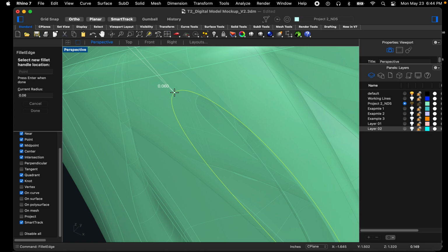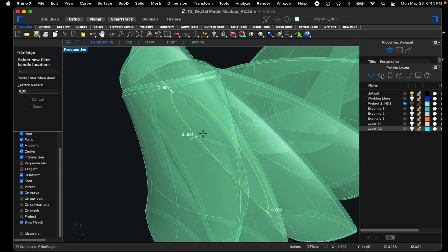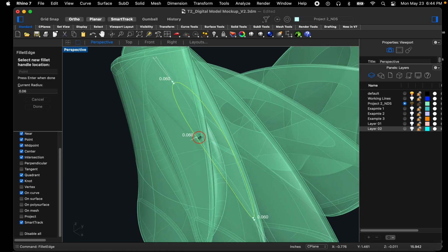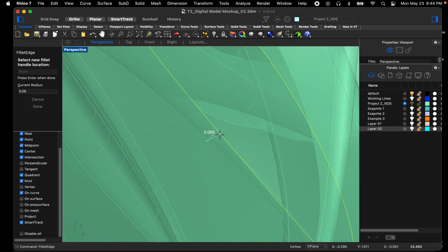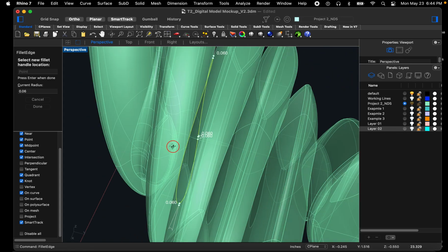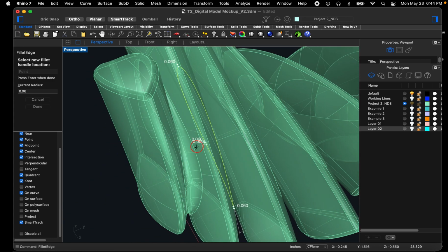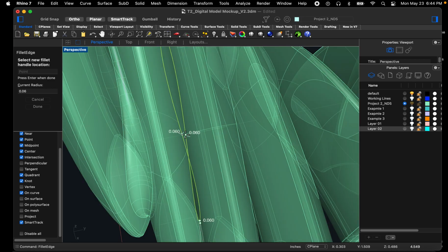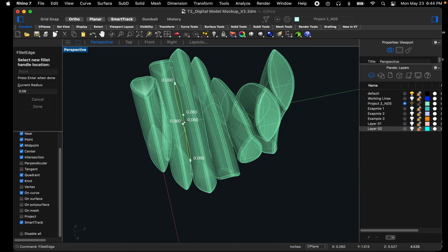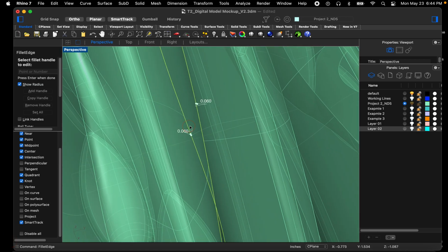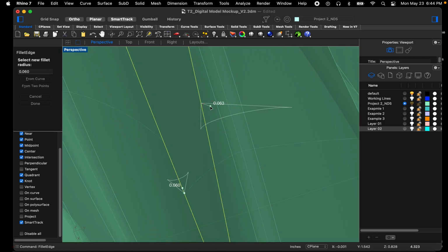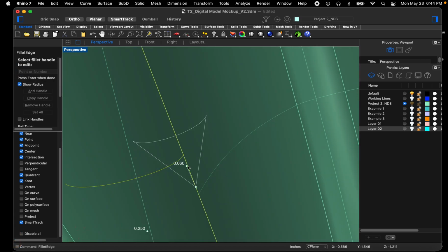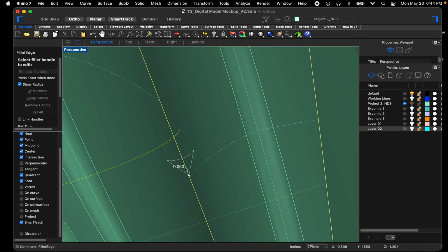Now, there is a real issue though. Okay? The more complex geometry that we model, the harder it is to maintain a closed poly surface, a watertight model, specifically for 3D printing. It is not impossible. It is definitely not impossible. It is just much, much more challenging. Because it really comes down to how you end up modeling the geometry.